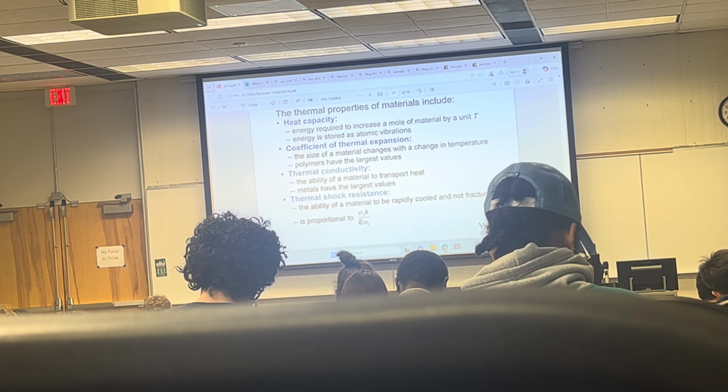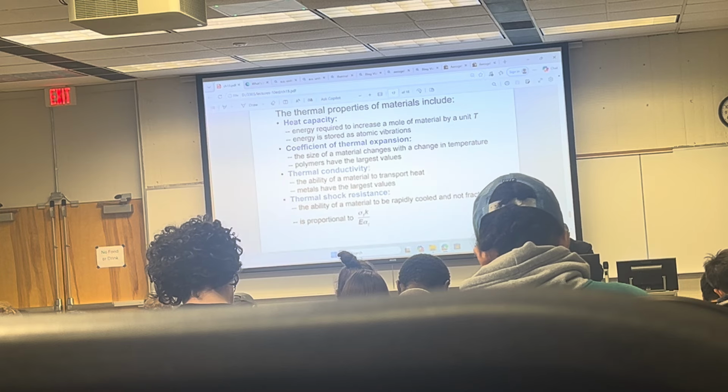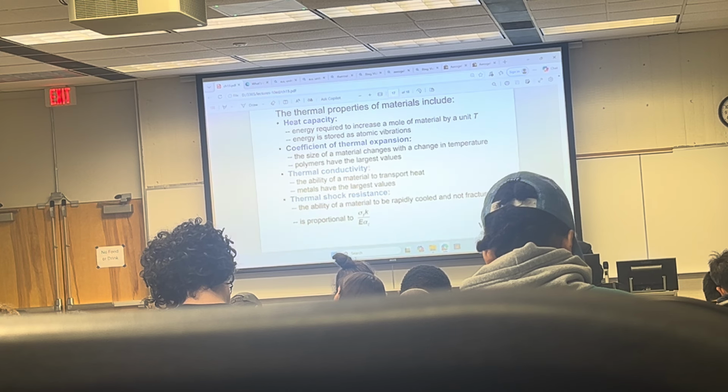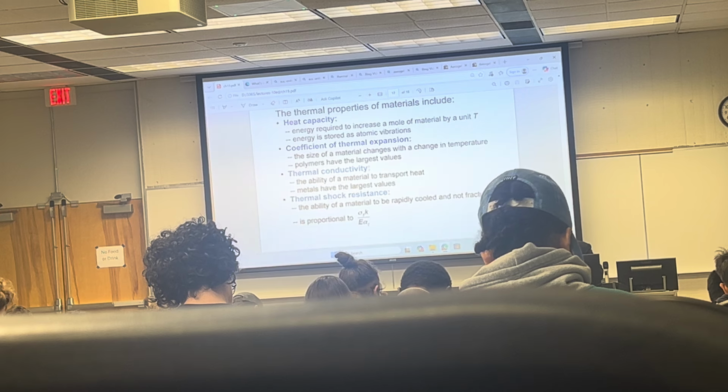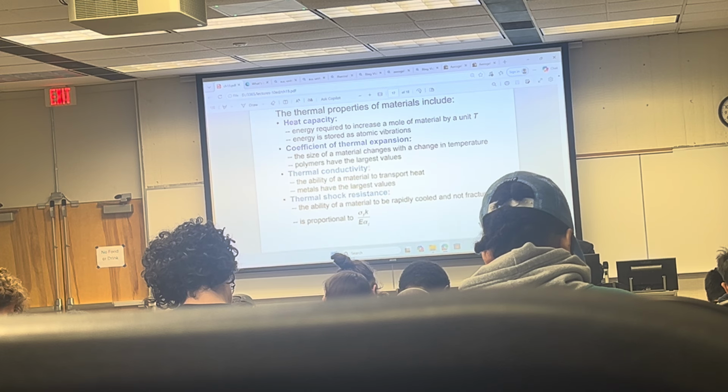Another problem. It's a large particle composite, so it's like chapter 16. You have the volume fraction of the particles in the matrix. You're asked to calculate the upper limit of the specific stiffness of the composite, and you're given the data for the materials of the particles and the materials of the matrix.